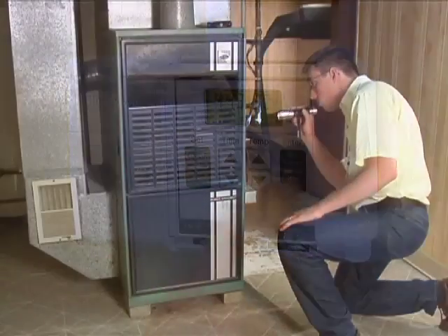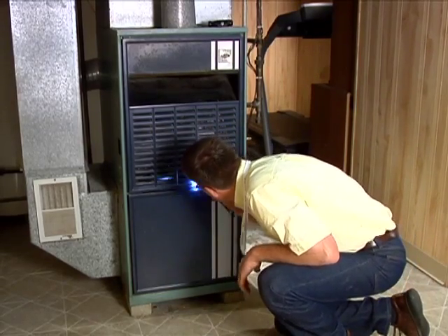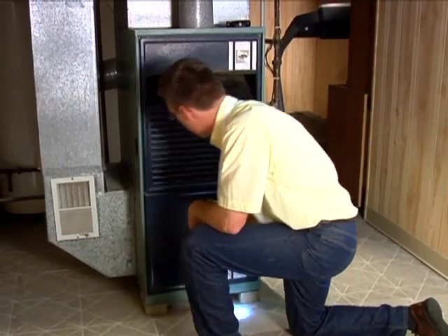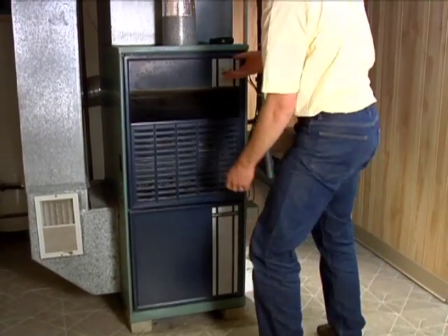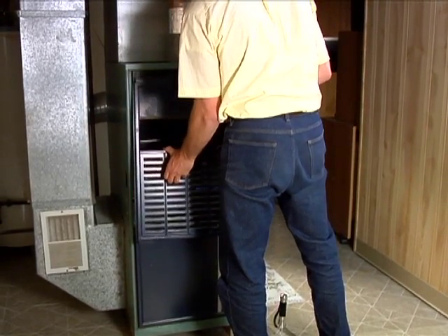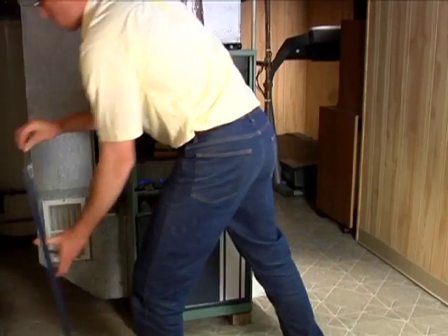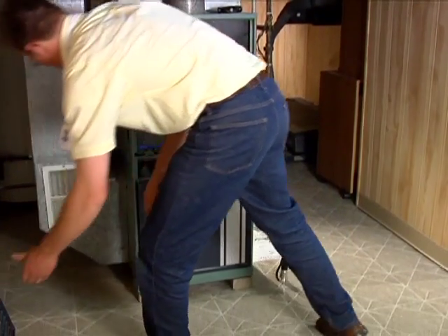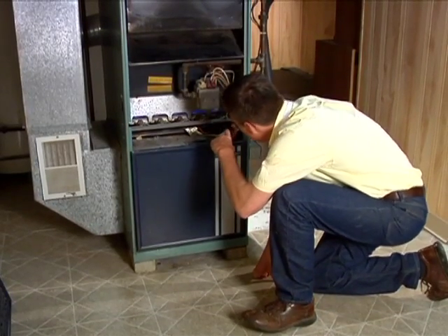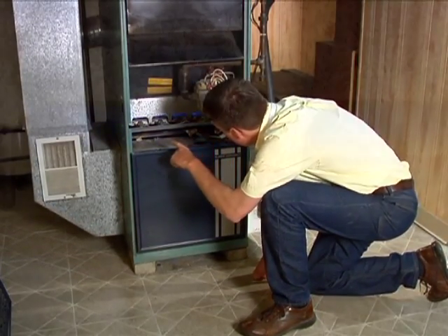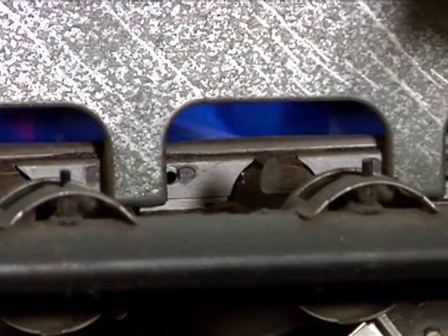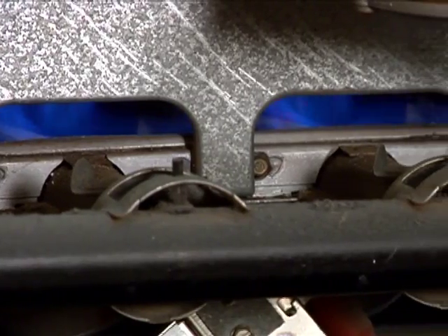Go to the furnace, bring a flashlight and a 6-in-1 screwdriver, and wait for the inducer motor to turn on, if the system has one, and the burners to light. Remove the door cover and perform a visual inspection of the entire furnace, flue, and vent system. Look for flame rollout or other performance and structure issues which may cause improper working conditions. The furnace flames should burn consistently, and you should hear a steady noise of the burner and blower fan.